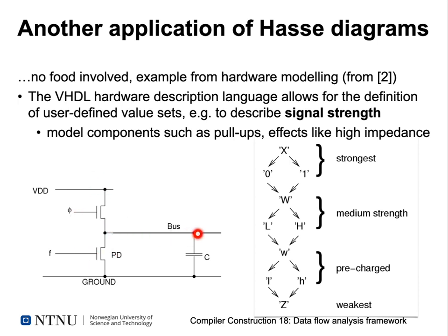So you might have a bus carrying a common bit signal here. This bus has some capacity, so there's some charge on the line that might try to influence your signal. Essentially what you might have here is a function defining the switching behavior of your lower FET transistor, and maybe a clock defining the functionality of your upper transistor.